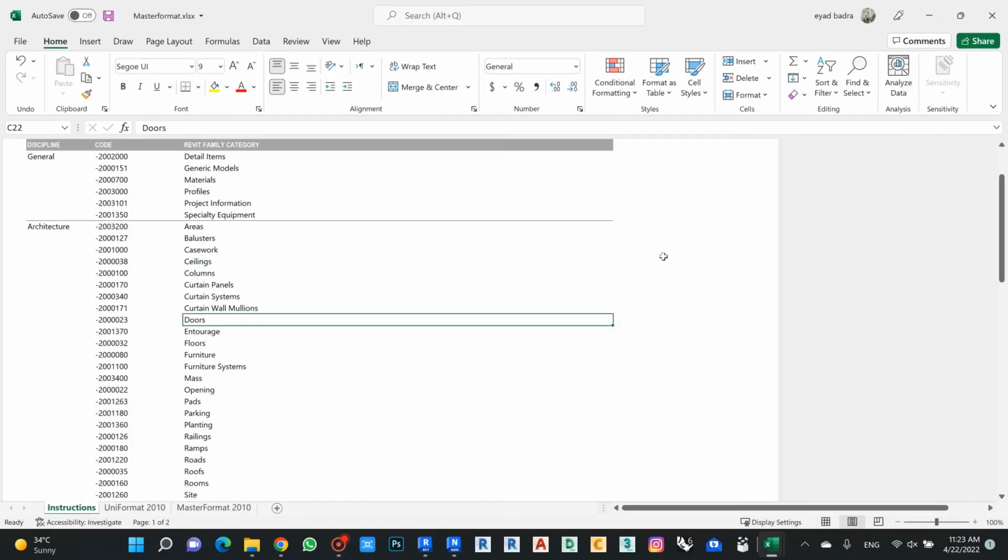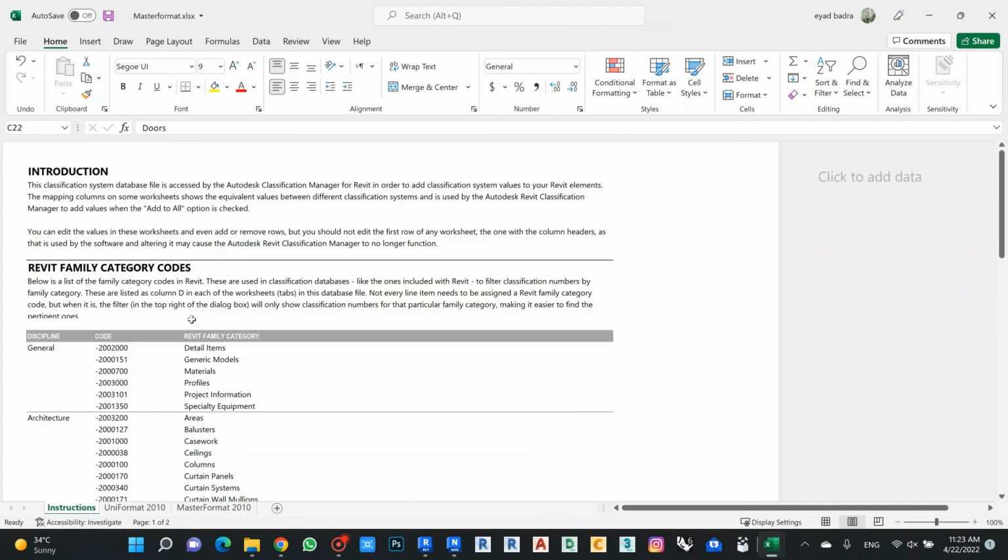So that's it. I hope this video is useful for the quantification and the MasterFormat between Revit and Navisworks and how to get the final quantity for the material that I have in my project. The most important thing is that when you start to use it in Revit, before putting any elements, you need to add all the assembly codes and add the assembly description and decide what the form of the assembly code will be that we'll use, MasterFormat, Uniformat, OmniClass, directly from Revit regarding your company or office.